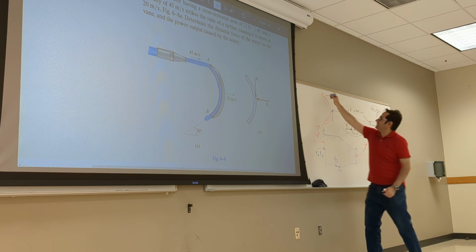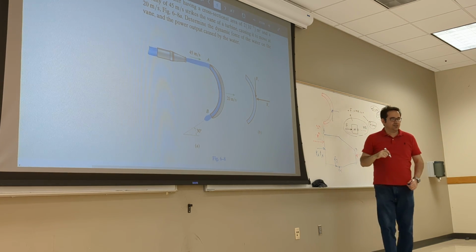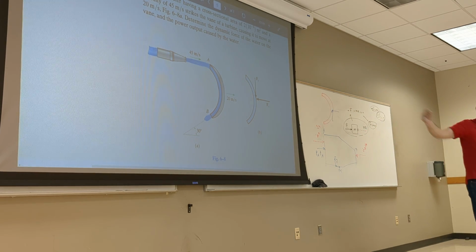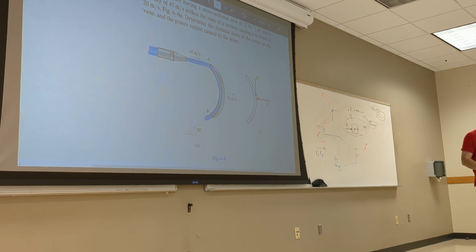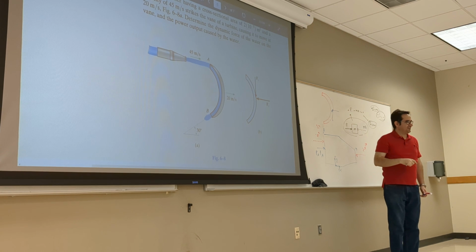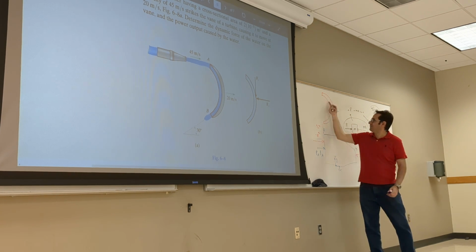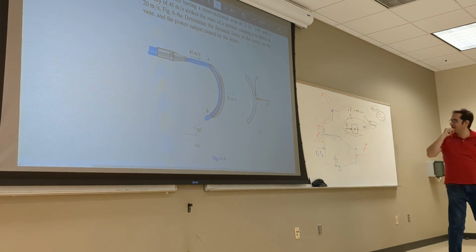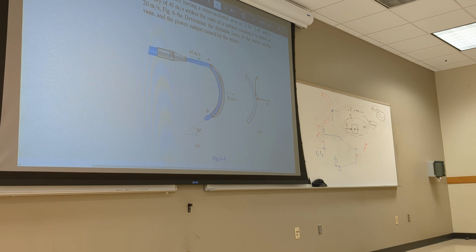Do I have pressure here? No. Why? Because it's in the atmosphere, it's exposed, it's not inside the pipe. So no pressure force here, no pressure force here, right? And nothing else, everywhere atmosphere. And then you will get confused, right? Everything is zero. Summation of force in that is zero. But look, he doesn't put the inertial load on the FBD. He just puts it in the equation.